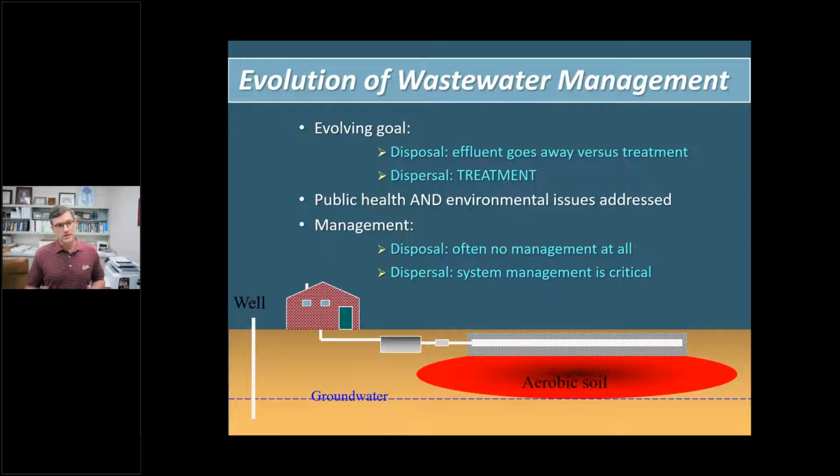We're not necessarily trying to treat it on site compared to the dispersal of having a treatment. And as we note on here, there are some public health environmental issues. And then from a management standpoint, disposal, as we said, not really any management at all. And dispersal system management is critical. So when we think about putting these systems or tanks in place, the desire is that we're actually treating it with a safe disposal.